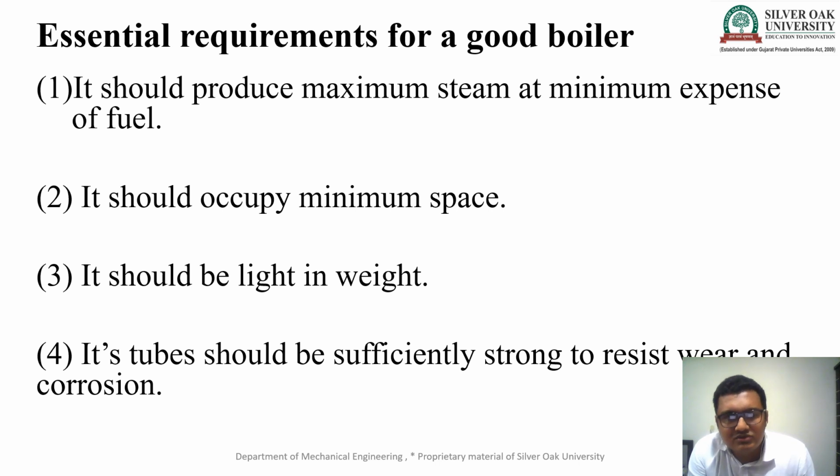Third, it should be light in weight, so transportation will be easy. Fourth, its tubes should be sufficiently strong to resist wear and corrosion. The material of the tube which we use inside the boiler should be sufficiently strong to resist wear and corrosion.